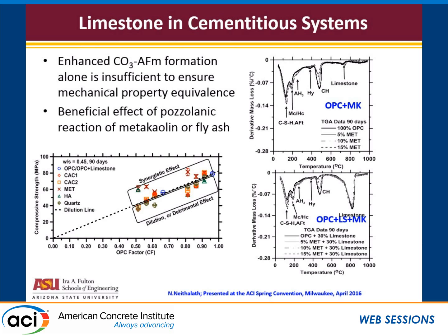So this is a derivative thermogravimetric analysis trace taking all the way to 1000 degrees Celsius. Jason showed one of these too, the same idea. So you have your calcium hydroxide. So here's one point again, it's a nice segue that I'm presenting after him than before. So I can take a lot of stuff from what he said already. He showed a lot of details on what calcium hydroxide is happening. He eventually showed you, if you remember, that if you add only limestone, you have excess calcium hydroxide in the system, right? Every other pozzolanic material, you have calcium hydroxide consumption. Limestone alone was negative in that chart. The exact same idea we're showing here, but in a slightly different way. This is glass half full story now.